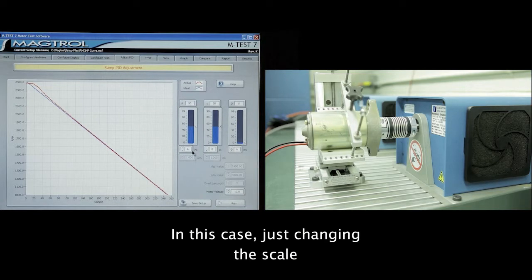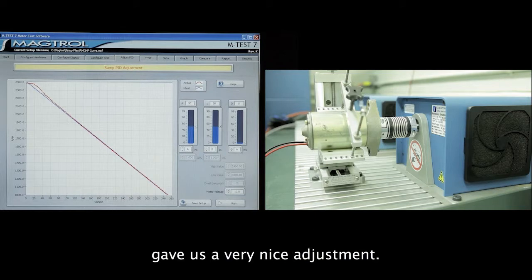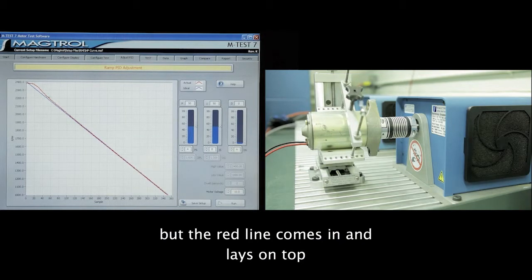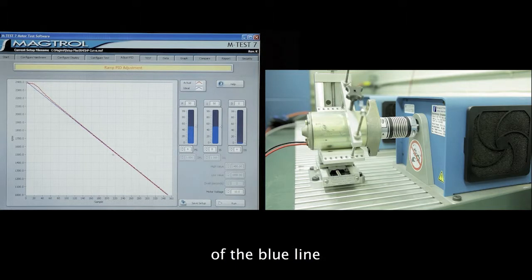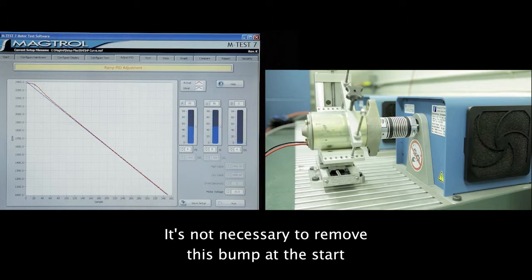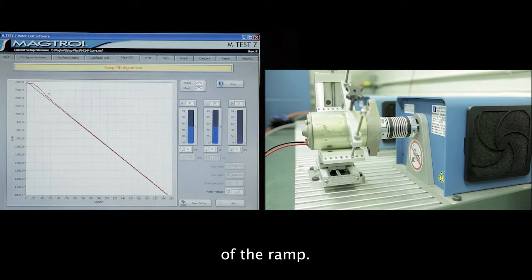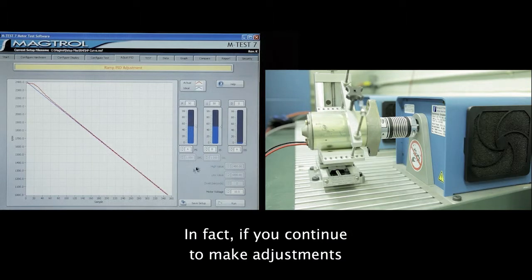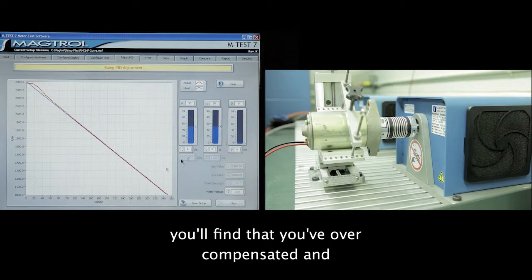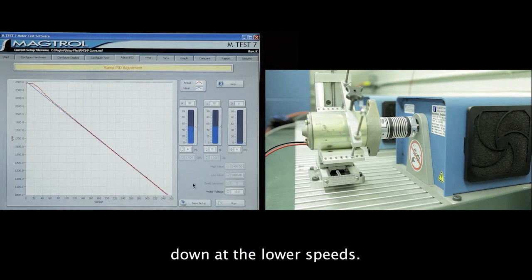Now in this case, just changing the scale gave us a very nice adjustment. There is a small amount of what is called a jerk at the start of the ramp, but the red line comes in and lays on top of the blue line for the rest of the way down, and this would be pretty much an ideal adjustment. It's not necessary to remove this bump at the start of the ramp. In fact, if you continue to make adjustments to remove this, you'll find that you've overcompensated and your system will probably become unstable down at the lower speeds.